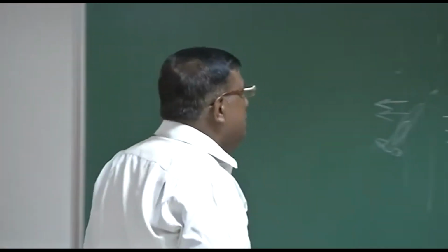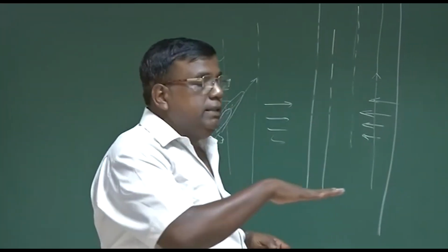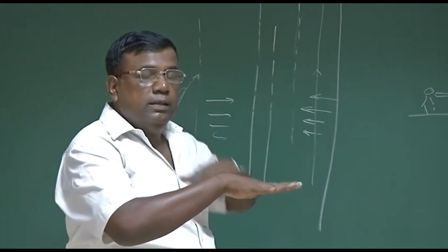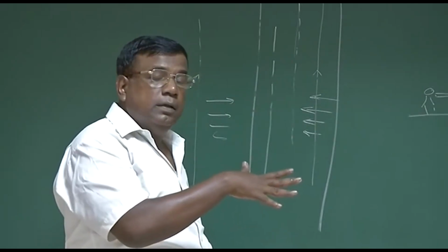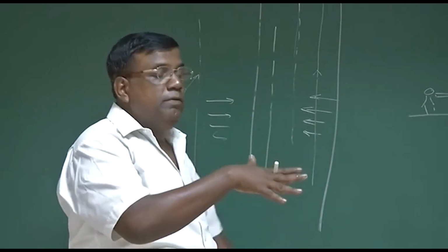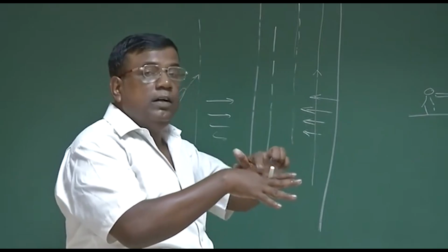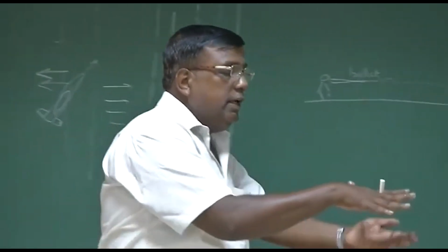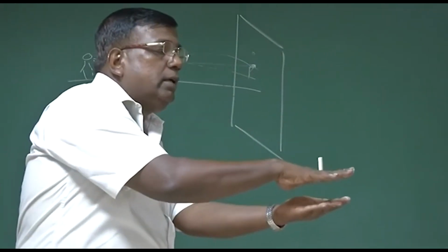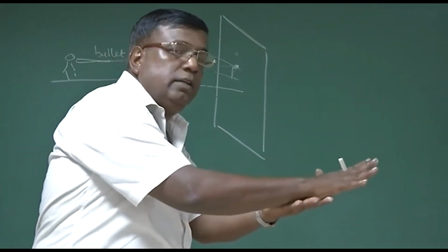Right, this is one way. The second way is I am flying like this and the wind is coming from my right, so I'll be drifted like this. What I do is bank my airplane. Once I bank it, the lift vector is like this. One component of lift will try to resist this drift. And I go like this, and near the airstrip, I roll back, flare up, and touch down.